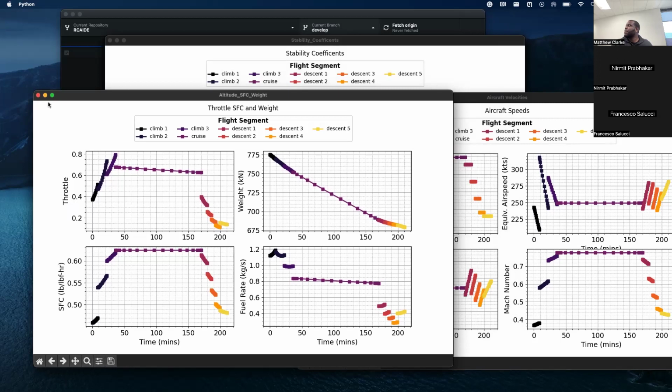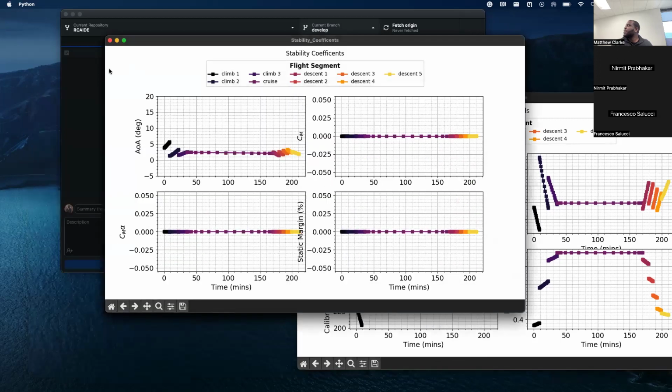You can get the specific fuel burn. You can get aerodynamic properties. These have been validated by, I don't know, several different places, Ryanair, Embraer, you name it. So these are pretty standard for the 737 aircraft. We don't do any stability. We're not going to model any stability in this simulation, so we just have it at 0 for now.